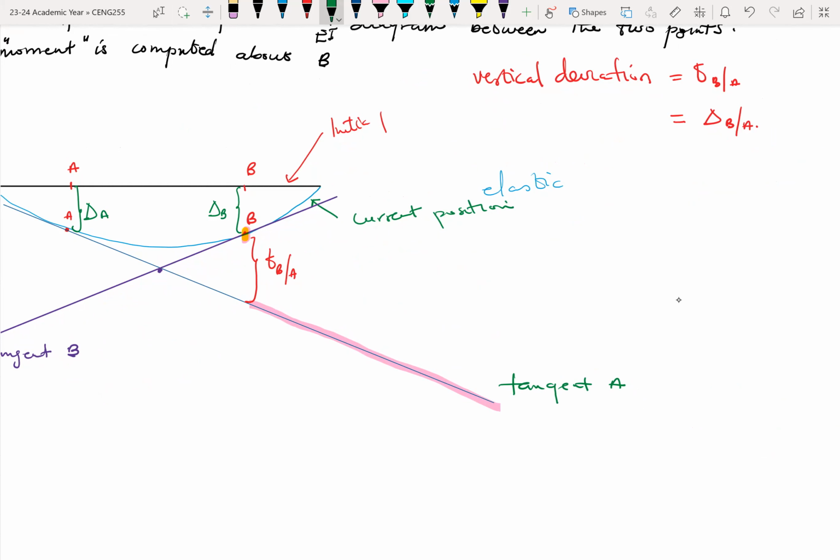All right. So once there's that deflection, we have the elastic curve forming, and delta B and delta A become those two deflections. The moment area method doesn't straight away find these deflections, as compared to the double integration method, where once you are done with your integration, whatever answer you find will be the deflection of that particular point.